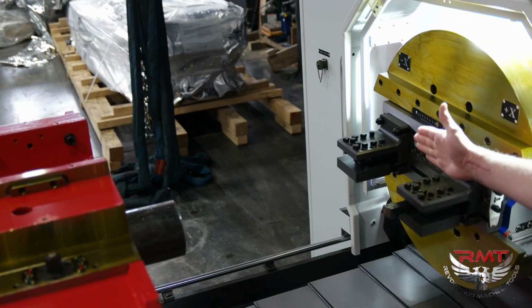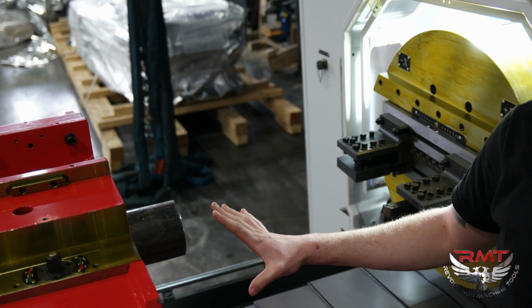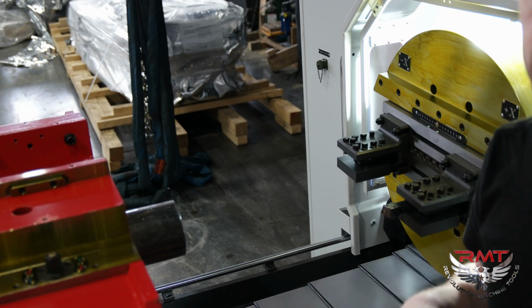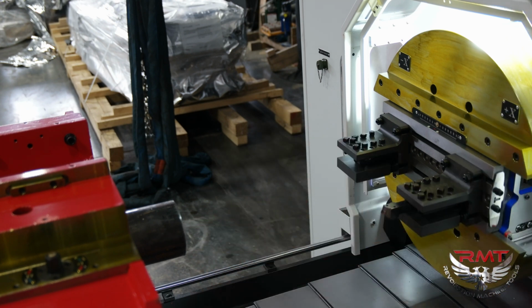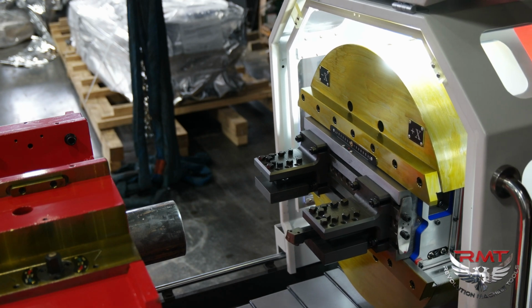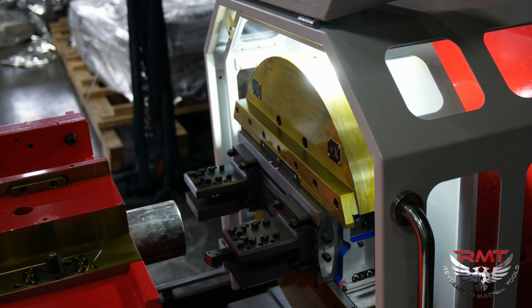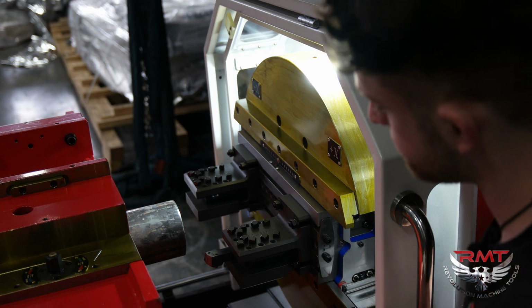Now, what I'm going to do is I'm simply going to jog this up close-ish, and then I'll do some fine-tune adjustments before I actually turn on the spindle. So while in jog mode, I'm going to bring my Z negative until I get reasonably close. Then I'm going to switch over to my handle mode and use my jog box to get in closer.